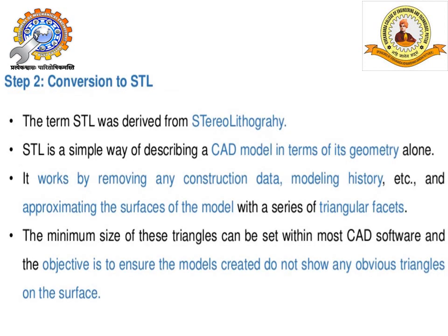Step 2, conversion to STL. The term STL was derived from stereolithography, which I'm going to explain in my next session. STL is a simple way of describing a CAD model in terms of its geometry. It works by removing any construction data, modeling history, etc., approximating the surface of the model with a series of triangular facets. STL is also abbreviated for